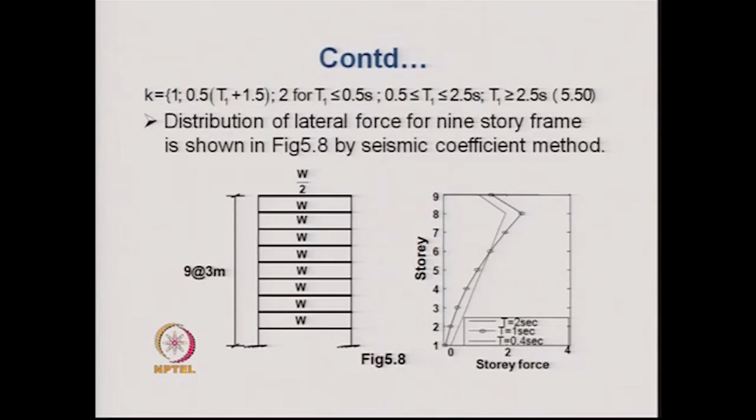The figure shows that the variation of the story forces, that is the forces distributed along the height of the building, varies non-linearly for time period equal to 1 second, for time period equal to 0.4 second and 2 second. These variations are mildly nonlinear.